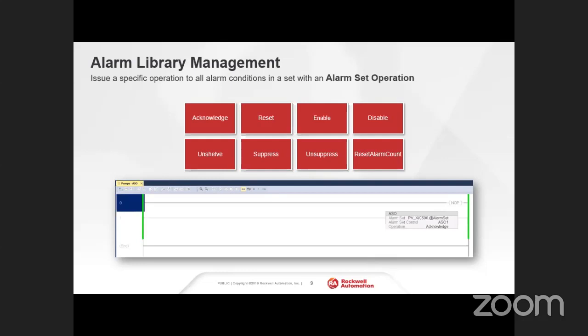And for anybody that's asking, this is something that we added in 31. We've talked about it in the past in the user groups. So with an L8 and the 5380 controller as of V31, they added Logix tag-based alarms. So this is the functionality. This is now an upgrade essentially to the feature set that was introduced in 31 that we now support in 32 to get you the same feature set that you would have at the HMI level, but now inside of the controller and being pushed from the controller to the HMI. Exactly. Yep.